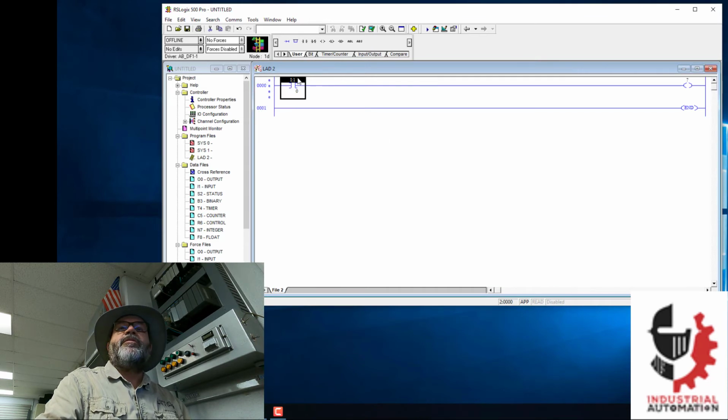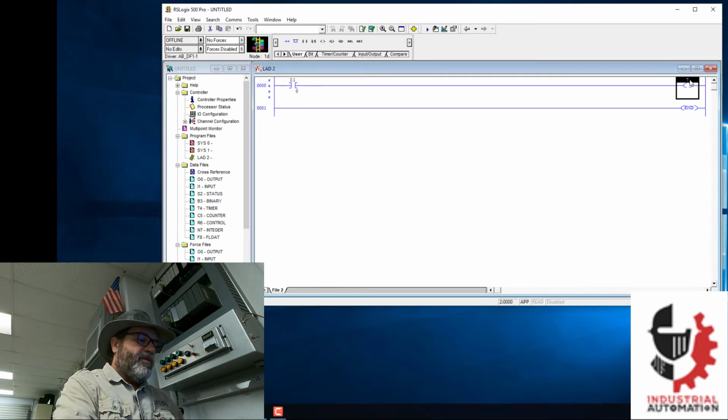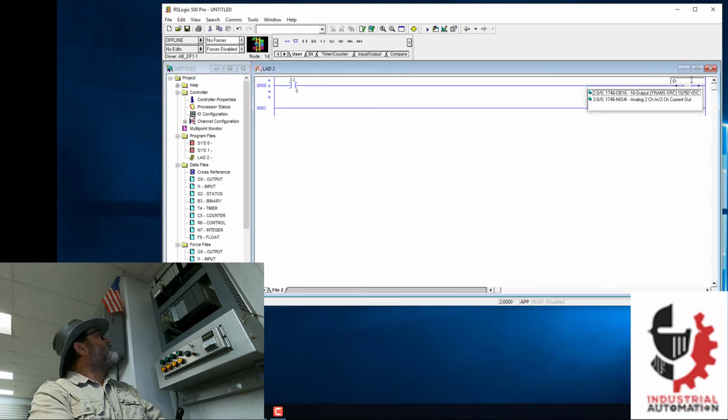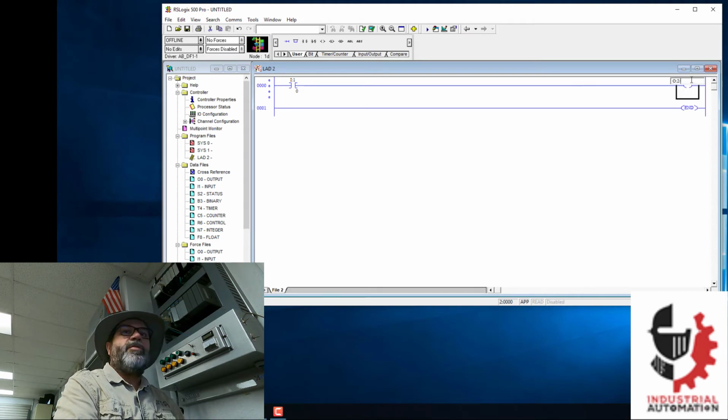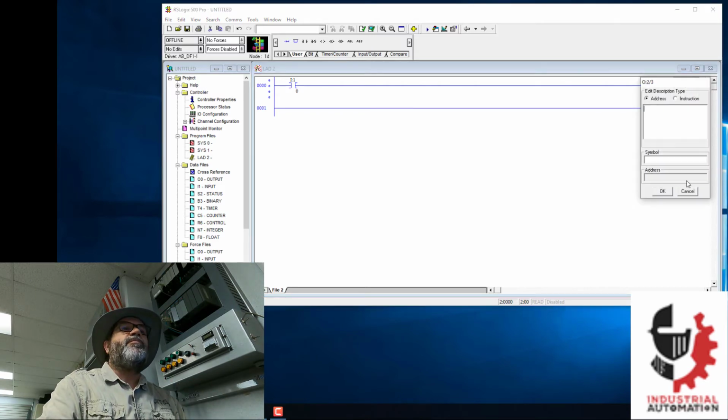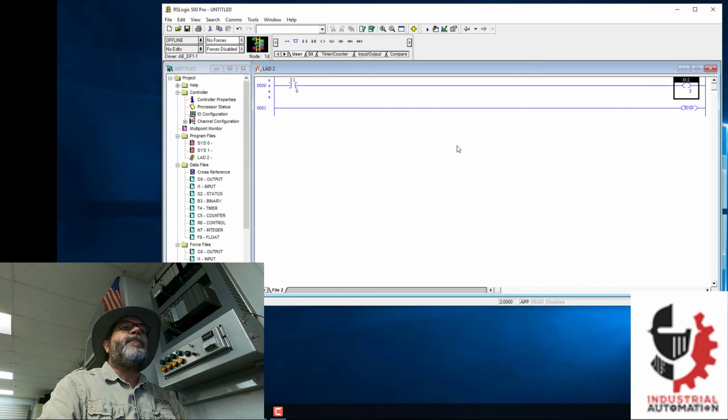For my output, I'm going to use O:, and my outputs are in slot 2, 2/, and I'm going to use number 3 for my output. And hit Enter. Again, I'm not putting in a description yet. And now I want to download my program and go online.